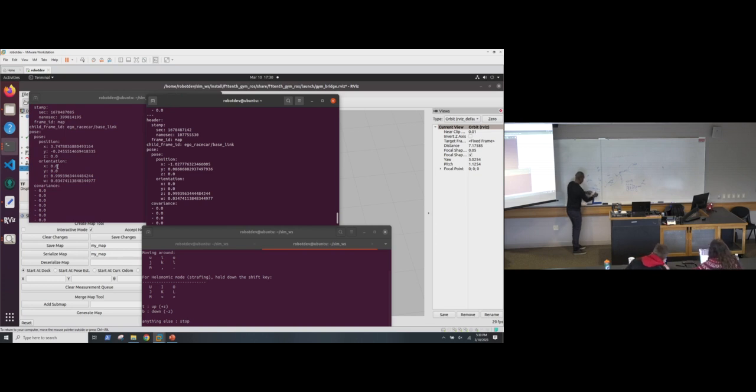I could do this in the CPU, but I could do this in the GPU really fast. And now I know where my orientation is. And I can extract my roll, pitch, and yaw out of that, or my quaternion vector in this case, and I could extract my X, Y, Z position out of that. That's called a transformation. So that's how you go from one point to the other there. And we do that a lot in robotics.